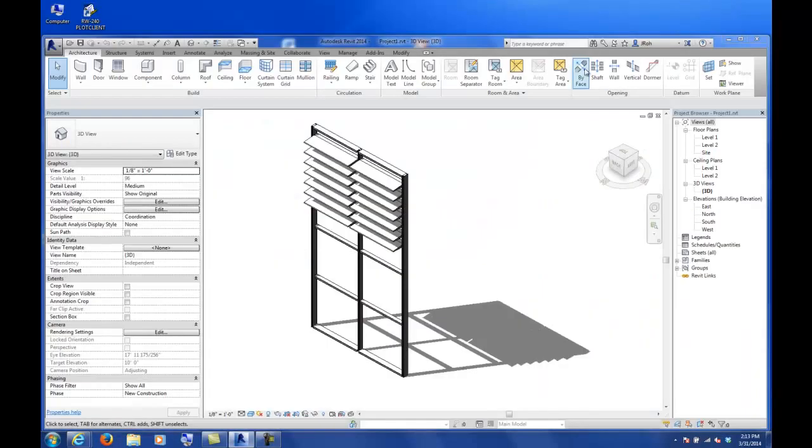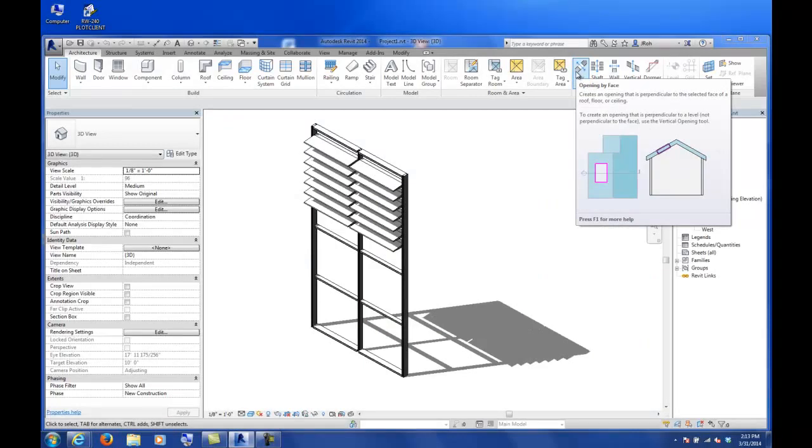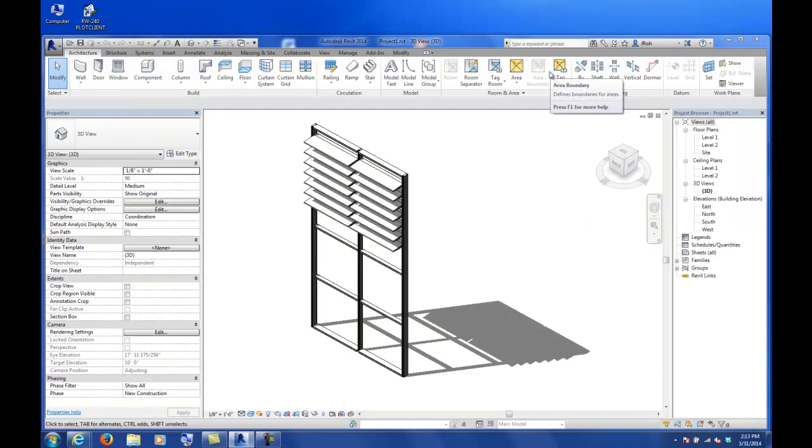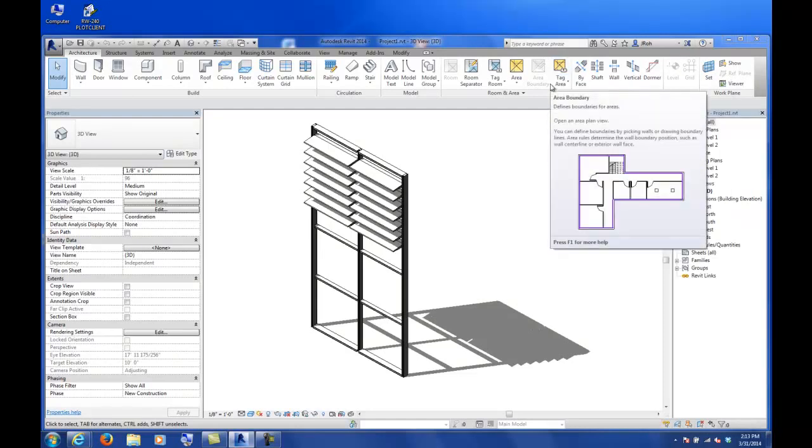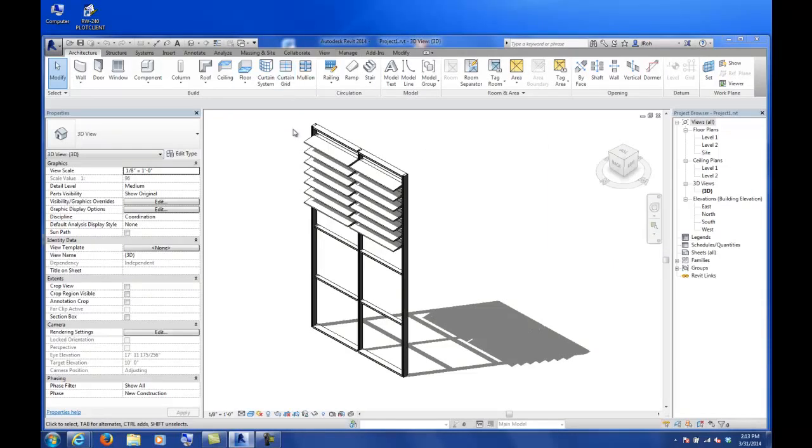Today, the focus is going to be on using the railing tool and the stair tool, but I can't talk about railings and stairs without first talking about parametric profiles, because in order to really use anything within this part of Revit, you have to understand the 2D profile. And because we're working with the 2D profile, we can also use that to help customize our curtain wall systems, so that you don't just have your typical curtain wall.